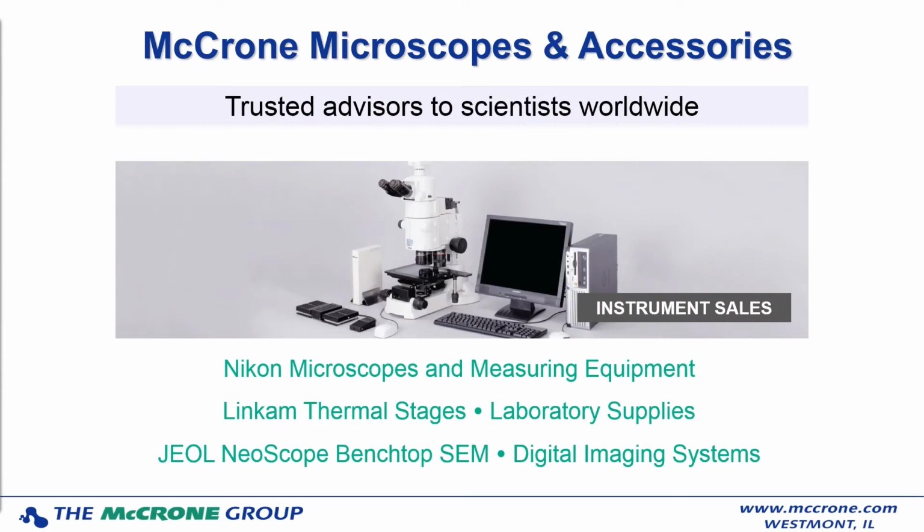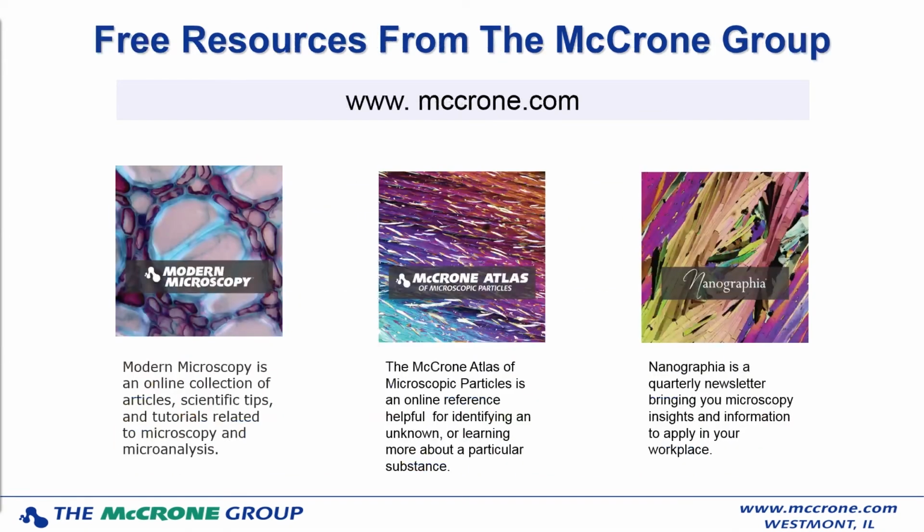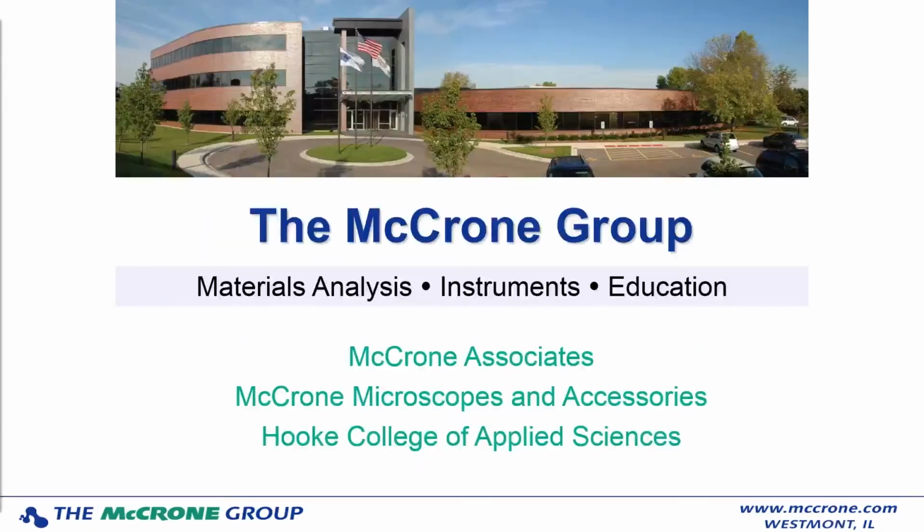Next question was, what kind of lateral resolution does XPS have in terms of mapping? Well, for mapping, this is similar to our previous answer in that the effective resolution goes down to about 10 micrometers. If you try and go below that, it really is limited to mapping major elements that have a large difference in concentration across the surface.